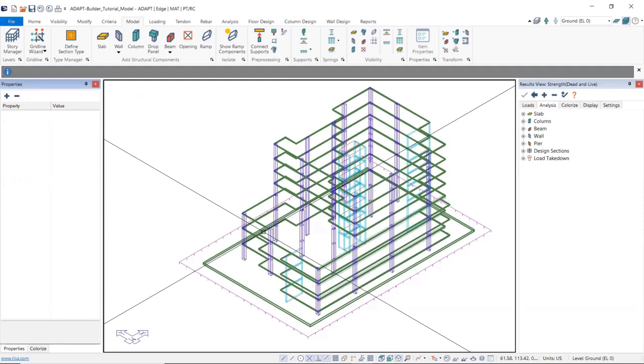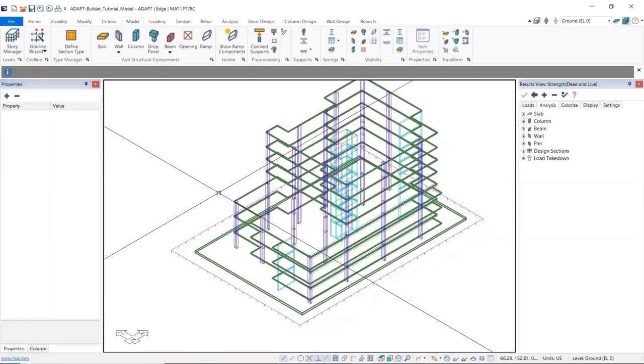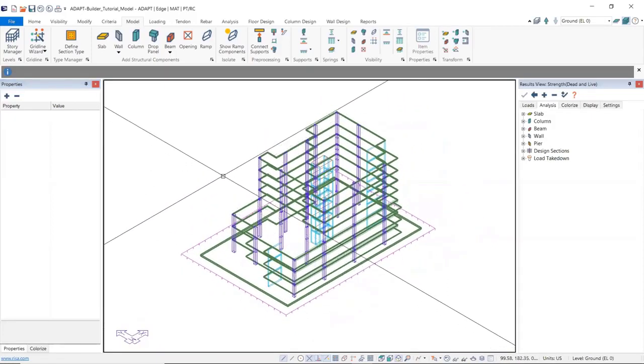Now, I'll have to analyze twice, but this saves me from having to use a gravity-specific model and a lateral-specific model. And as we all know, there's going to be change requests, and I don't know about you, but I'd prefer to just work with one model and only update that one model. It makes it much easier to keep track of those things. So that's usage cases.